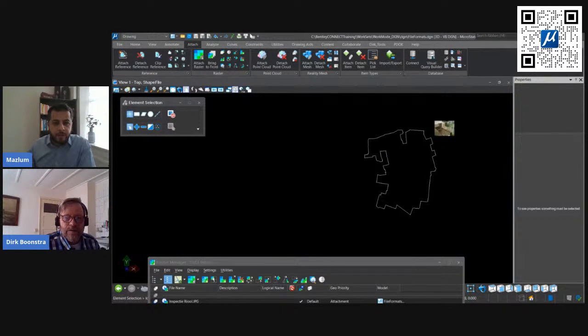Let's see, raster convert. Okay, so I think I talked enough about vector data and about raster data. There are so many possibilities. When you do have to do a conversion, try to do a direct one. If you have to go from format A to format C, don't go to format B and then from B to C. Go as direct as possible. Minimize the number of translations that you need to do. And when you don't need to change data, always use it in a reference. Now, there are more data types that MicroStation supports, and one of them is point clouds.